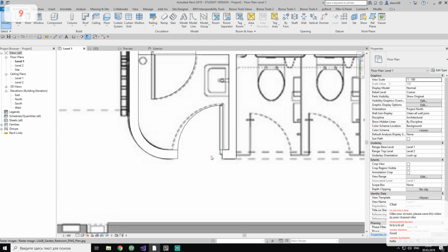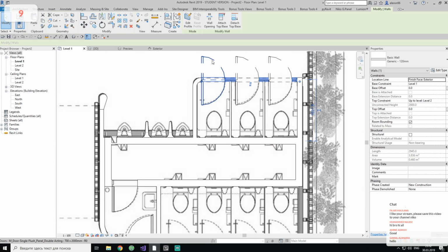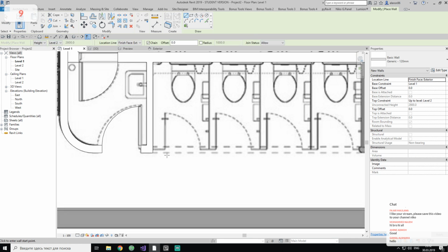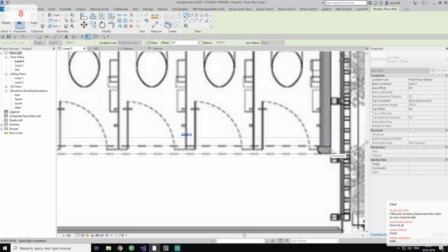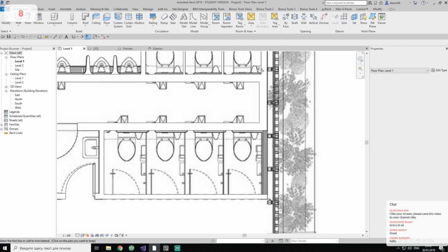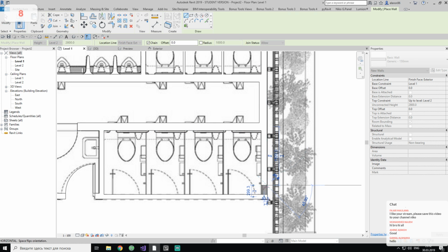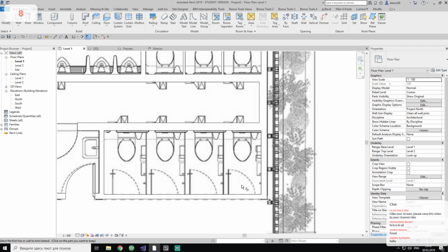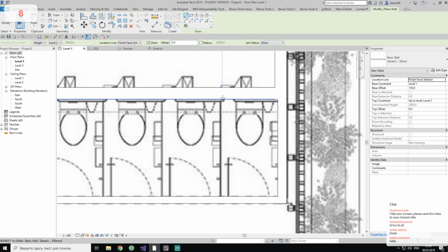So this is really simple. What we're going to do here, now I will copy this door again. As you can see, select the wall, select create similar, and after that just draw your door on the opposite side, like this. Okay, the same thing here, like this, trim, and one more time. Okay, we did it.